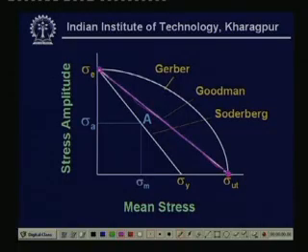This signifies that you have a line joining them, as before, guarding against the sigma ultimate value and the sigma endurance. In a similar manner, it has a name after Goodman, and this is called the Goodman safe line of stress.